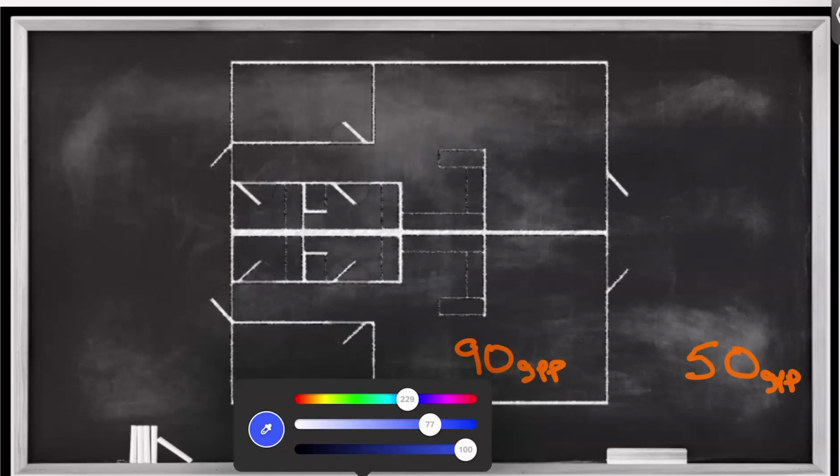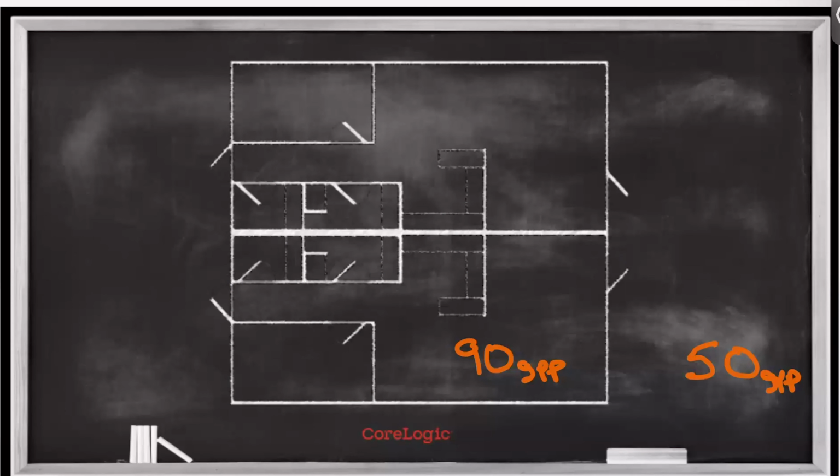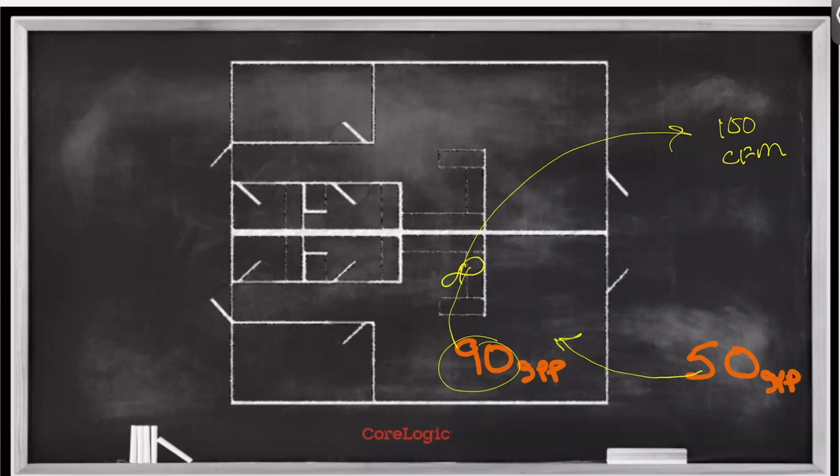I'm going to go in the kitchen and turn on this kitchen exhaust fan that is going to vent air out of the building at 100 CFM. By dumping this 90 GPP air out at 100 CFM, we're going to draw outdoor air in at 100 CFM, right?